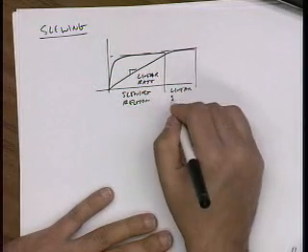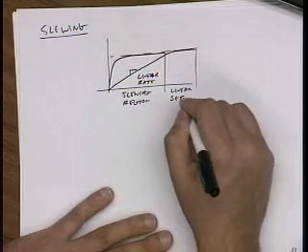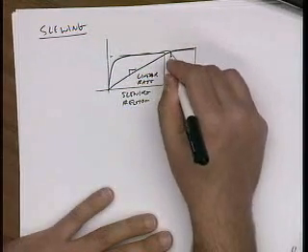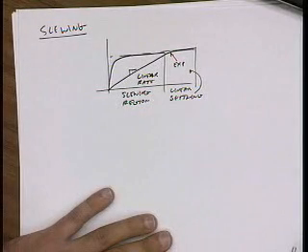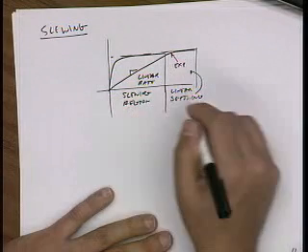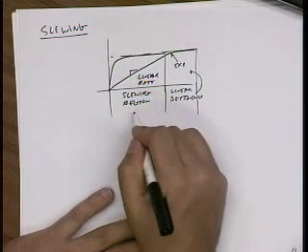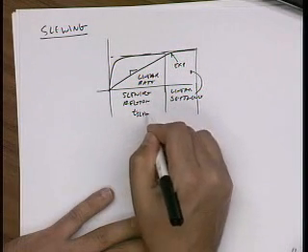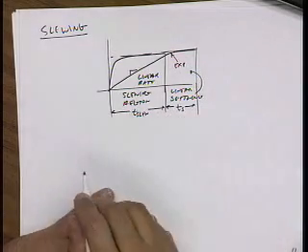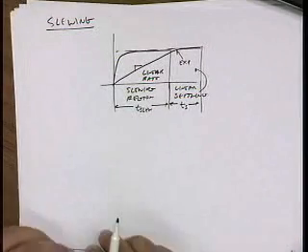Kind of a bad term, right? Because this kind of looks linear, and linear settling gives me exponential. So in general, when I design amplifiers, unfortunately, I have to make sure that I take the slewing into account. Otherwise, I may completely underestimate the actual settling time of the amplifier.